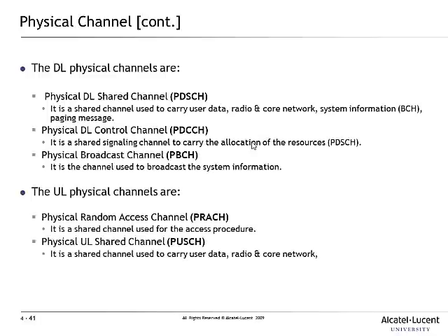And then in the physical channel, the important ones probably are the PRACH, which is the random access channel. This should be familiar to you. This is the channel on which you send a RACH message to be able to set up, and it's an uplink message.